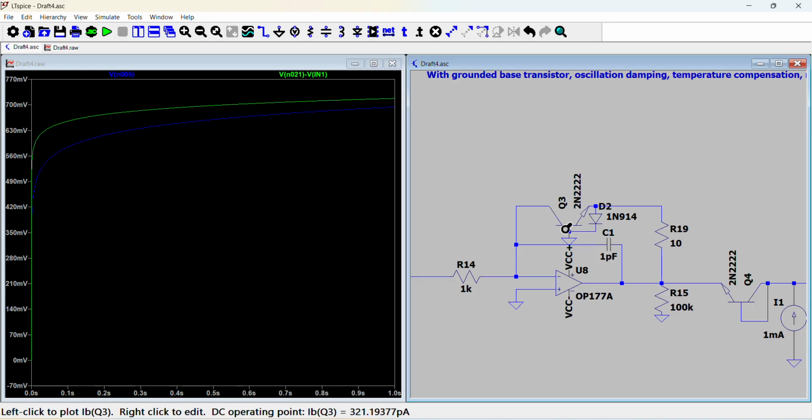it can actually reverse bias this PN junction through a Zener breakdown or avalanche breakdown, and it can damage the transistor. So therefore there's this diode here that shorts to the ground. In normal operation mode, the voltage here is always negative, so it's always below ground. So therefore you can never actually have this diode activated in normal operation, steady state.